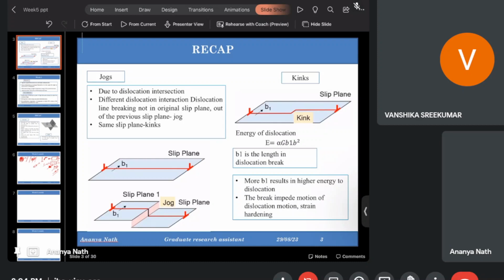Actually, we can increase the strength also by increasing the dislocation density. That means, if we are using some powder by making a groove, and we put the tool over there and weld, I think we are giving some cold work during the welding process.